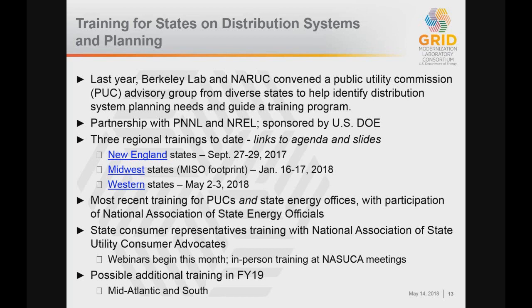Interesting question. I would say it's not considered overkill and it's not considered gold plating. The basic reason being that grid modernization is kind of an umbrella term, and it covers a lot of components. It's not just integrating solar, it's not just integrating renewable energy, but it's also equipment, new, shall we say, smart equipment, to use that overused word, that will help utilities figure out where problems are, fault isolation, so that instead of sending somebody out who has to drive the length of a distribution line, they can pretty much send a truck out right to where the problem is, or somewhere really close to it.